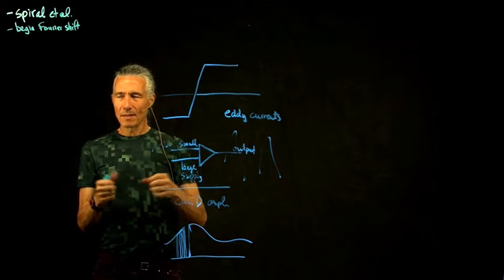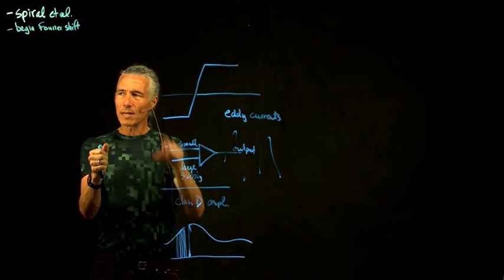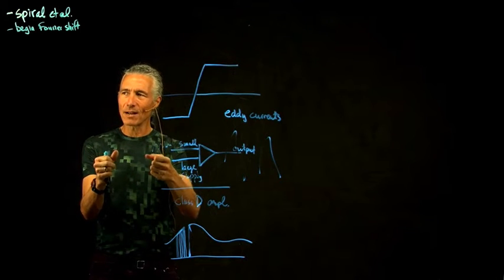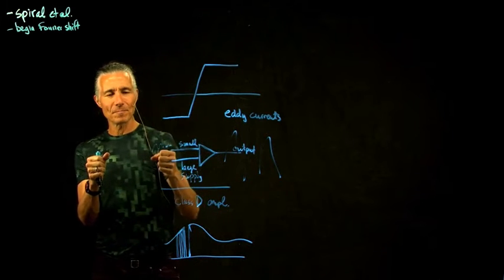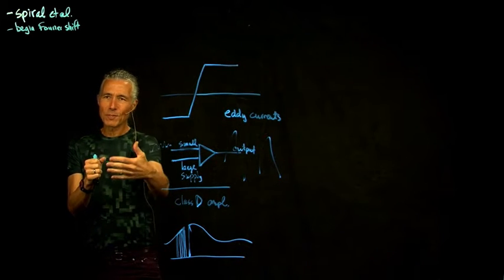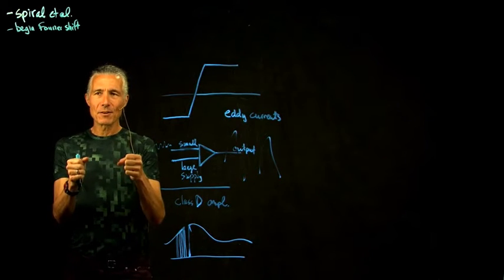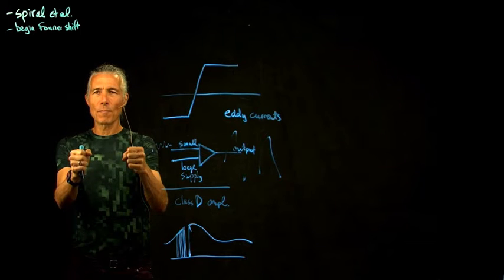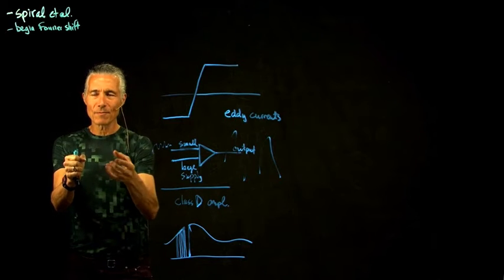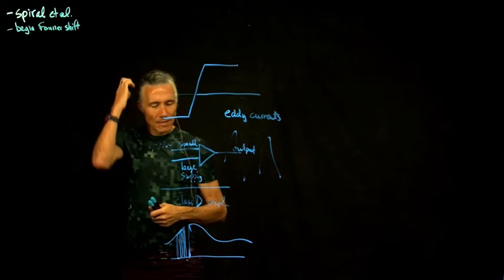But when you move those charges through the magnetic field, they start to rotate. It's low voltage, but a big current forms in that pie tin. It doesn't shock you or anything, but there's lots of current there. And then that current generates a magnetic field, and that magnetic field opposes the main magnetic field, the B0, that actually caused those charges to move in the first place. So you get a little pushback. If you stop pushing on it, there won't be any force. As soon as you move it, you cause charges to move, they make a magnetic field, that magnetic field is opposite to the main magnetic field, and you feel a push. So that's an example of eddy currents.